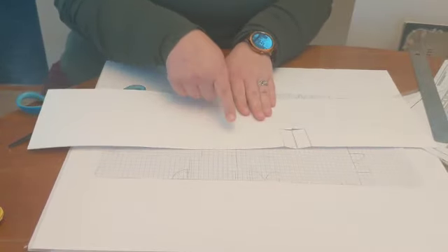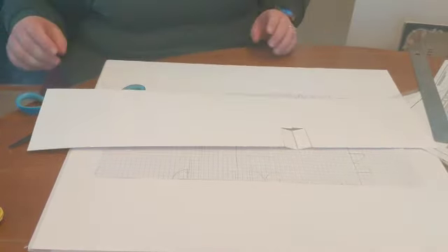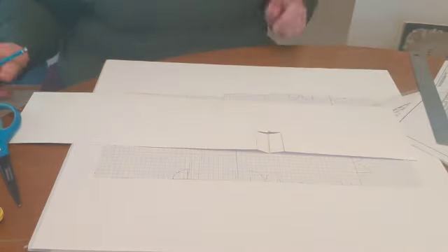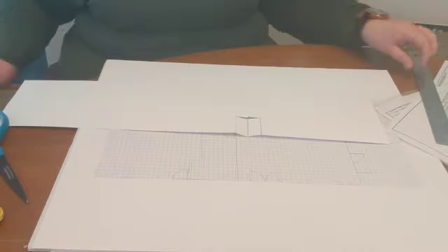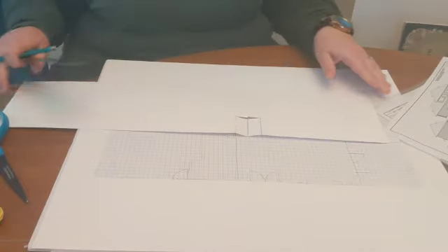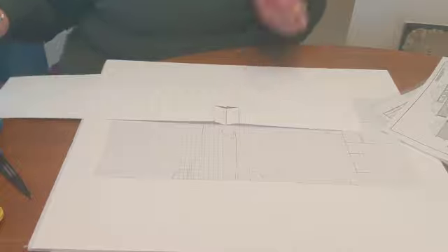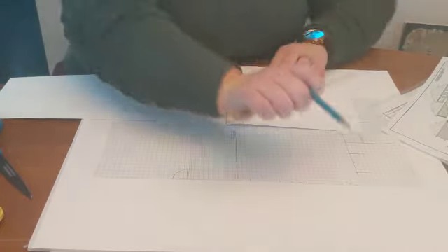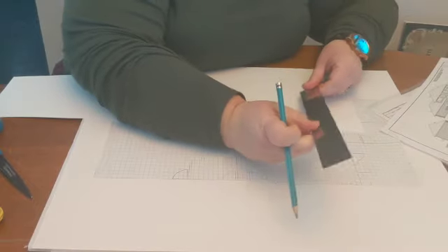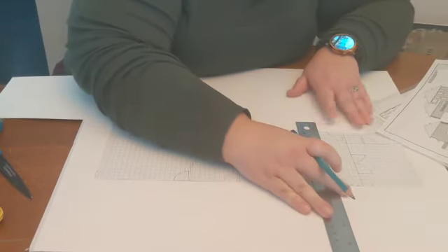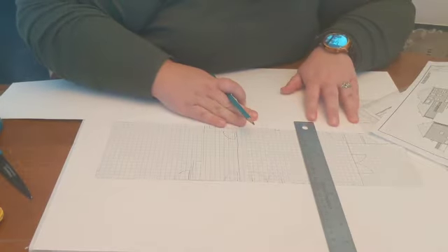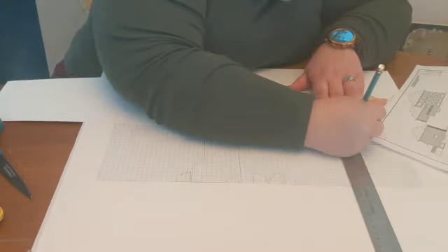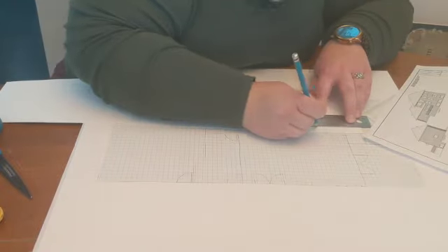So I have a door here, I would need to approach that the same way. Now for my windows, all you need to do is actually cut those out. So what you're going to be doing is drawing in your windows. Now each window needs to be at least 1 foot from the floor. I would say typically they're 2 to 3 feet from the floor. So for this one, I'm making the bottom of my windows 2 feet from the floor. You can make them at any height that you want as long as they look good.